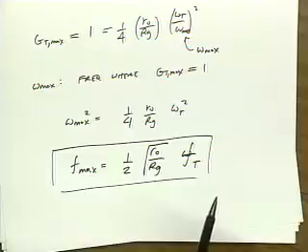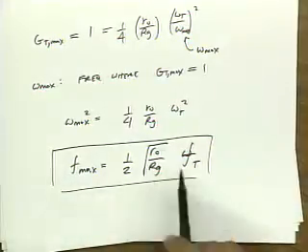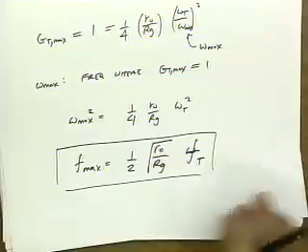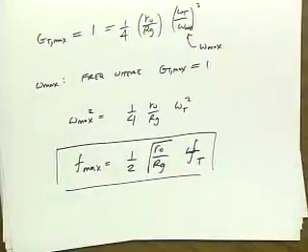Remember a couple of lectures back we said, why can't you arbitrarily tune out parasitics at a terahertz or 10 terahertz or a billion terahertz for that matter? That's because you won't get power gain out of your device. Actually, it's really hard to design inductors and capacitors at those frequencies, but in theory you could. You just wouldn't get power gain out of your device. Your device would be useless. It would just be a passive device, providing no power gain. Okay. Questions or comments about that?